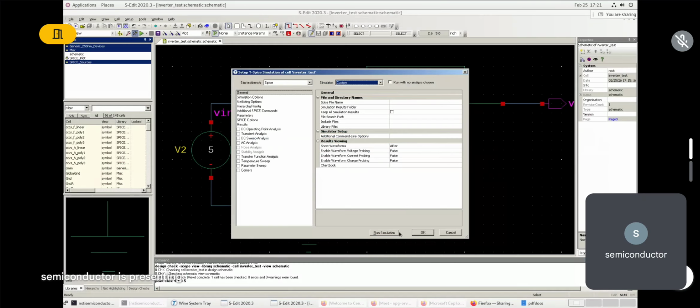Now here what we have to do is, you can see we have custom T-Spice and ELDO and AFS. Whenever you are doing small designs, don't go for Eldo analog and all. Better continue with T-Spice. Whenever you go for some operational amplifiers or something, go with Eldo. If you want to do mixed signal, it's a very advanced thing. For that, AFS is necessary. Now it's not necessary. You can go with the T-Spice only.